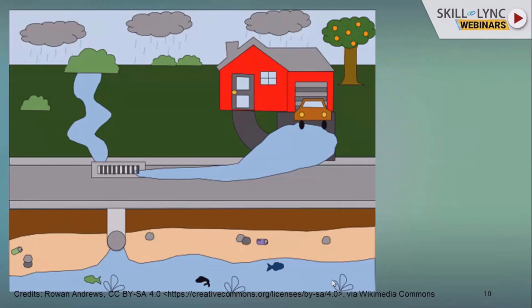our main criteria? That we should collect all this water, and we should collect the water in the catch basin. You can see these grating channels, which we call catch basins. And through the catch basin, we should discharge this water away from the city. So this is our main concern. When we design the network, when we design our stormwater drainage system, we simulate the same things: we make roads, we make catch basins, we make manholes, and we try to collect this rainwater into these catch basins, and we shift it away from the city. So this is our main concern.